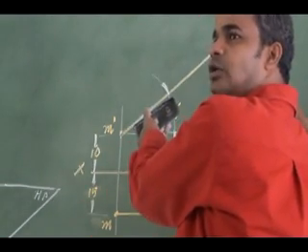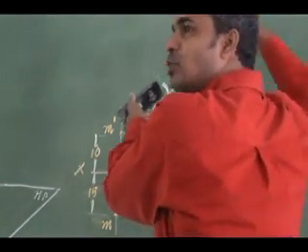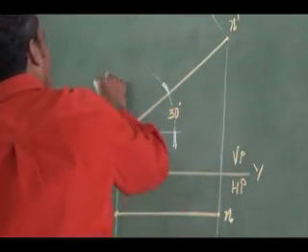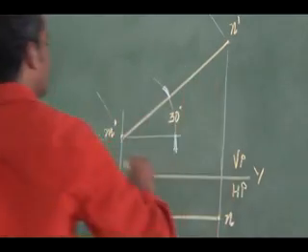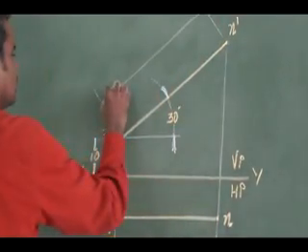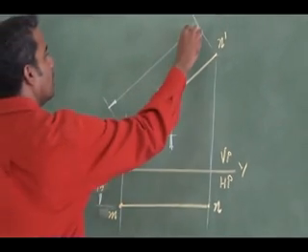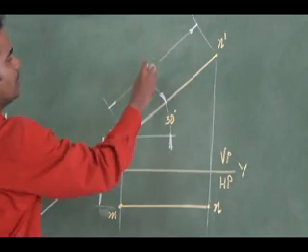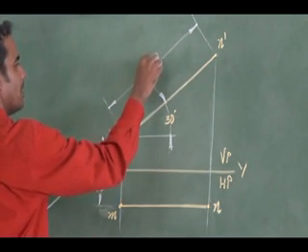Keep your drafter parallel to this. Use your other scale to draw the extension line, so I can draw an extension line neatly perpendicular to the line which you are dimensioning. So this will be my 65 mm.